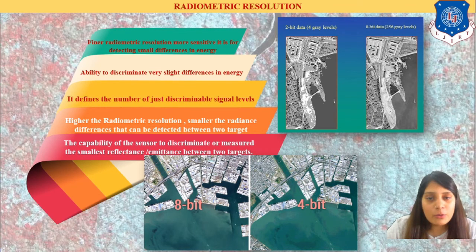Even in 4-bit you can see, but the pixel values and the pixels are clearly visible in 8-bit, which is known as radiometric resolution. So what I have explained is written here in the technical portion. You have to remember the technical portion behind radiometric resolution when it is asked for an explanation, right? So more bits will contain more layers of colors, and it will give us good information, good pixel intensity and good feature demarcation.